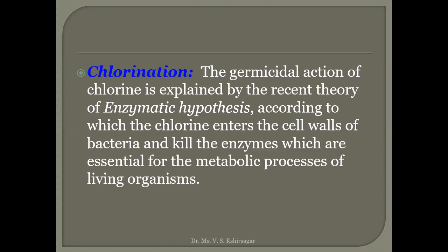Okay, so write down the next title, chlorination. Next method is the chlorination, and then in the next line you can write down the title, chlorination. The germicidal action of chlorine is explained by the recent theory of enzymatic hypothesis, according to which the chlorine enters the cell walls of the bacteria and kills the enzymes, which are essential for the metabolic processes of the living organism. Okay, please note down chlorination, and then we'll proceed to the next slide.